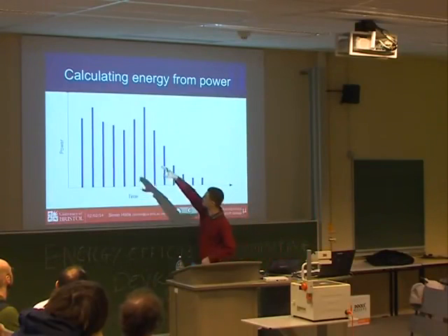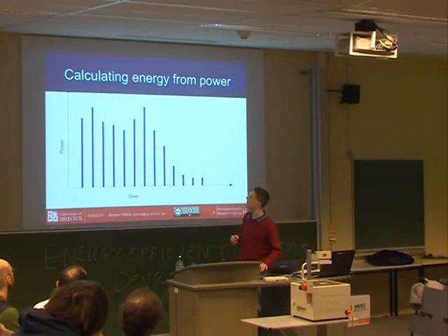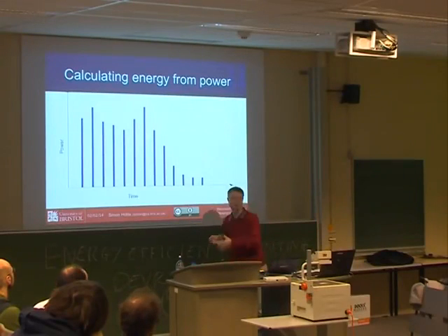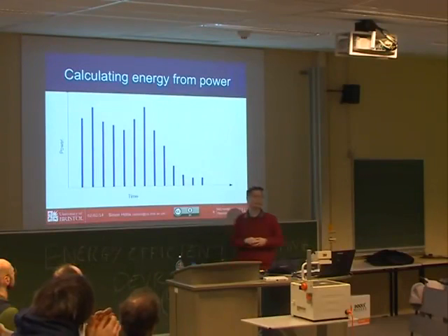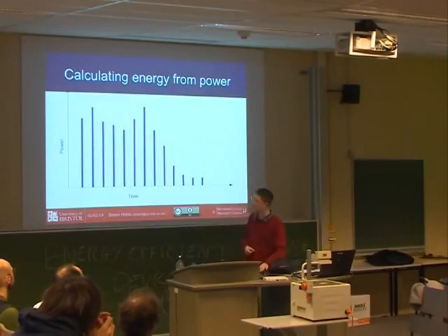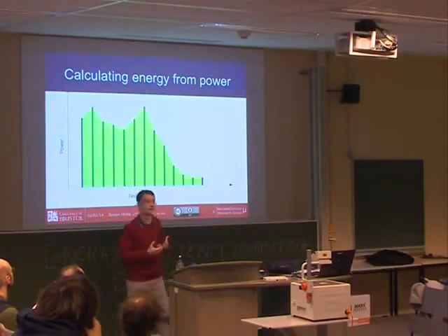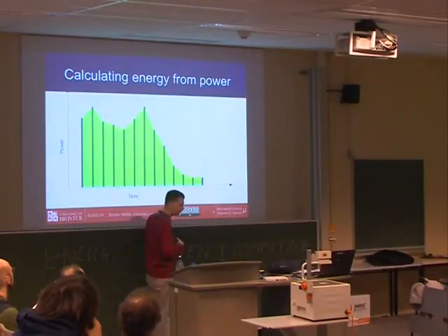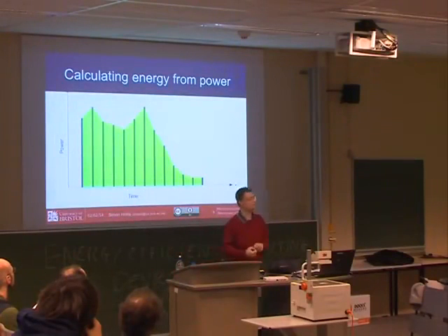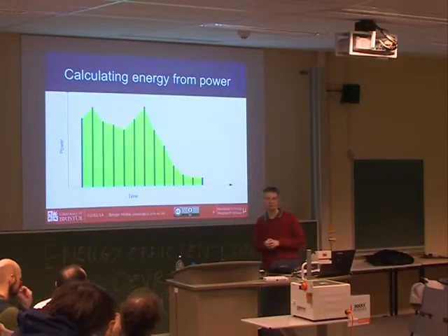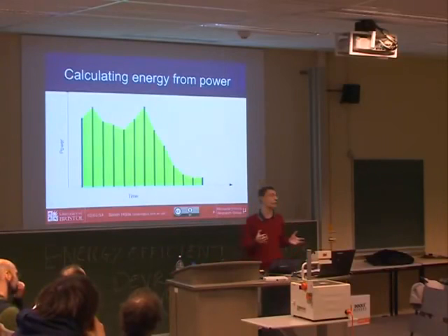You get the idea here is the system is taking a bit of power and then takes less power. And it varies around a bit. You can convert that easily into energy. If you have that set of measurements, you've got a set of power measurements now through time. You can say lots of things about the power consumption of the device. You can also then perform the integration process, which just measures the area under the curve, and now you have energy. So the area under the curve is the energy, from the measurements of power. So you get both at once. You just measure the power, and you have everything you need for energy, and more.